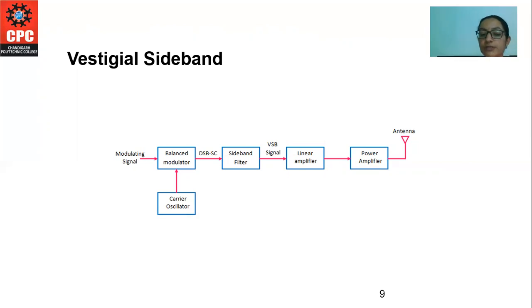That is, the transmission will be up to 0.75 megahertz without attenuation, and therefore the range of 0 to 0.75 megahertz of the picture is transmitted double sideband, and over the range of 1.25 megahertz and above, and in the intermediate range of frequency, 0.75 to 1.25 megahertz, the transition is made from one to the other.